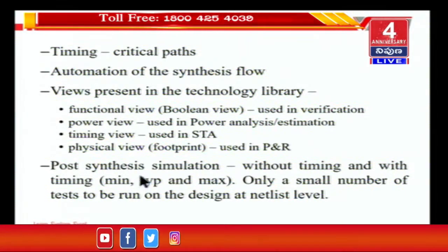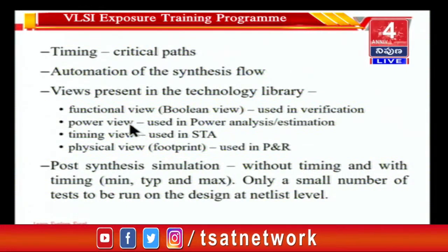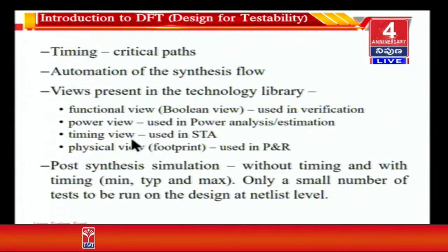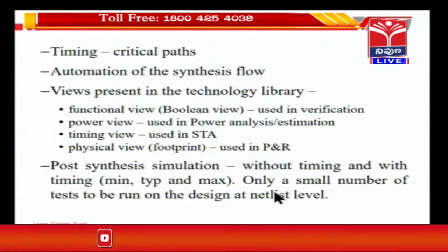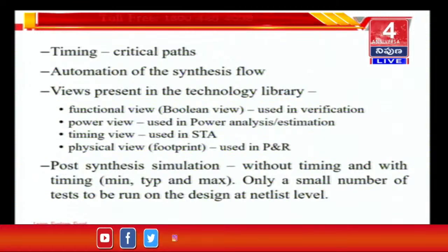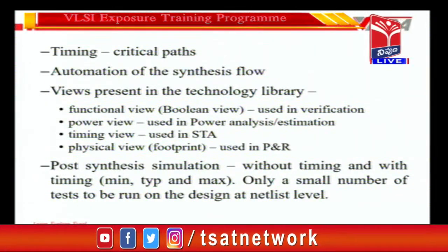Okay. Typical timing delays may not throw up all these things, but are used first only to find whether functionality is okay or not. To check for timing, these two corners are preferred, and only a small number of tests are run on the design at the netlist level. So what is it that you get out of the netlist, out of the synthesis step?